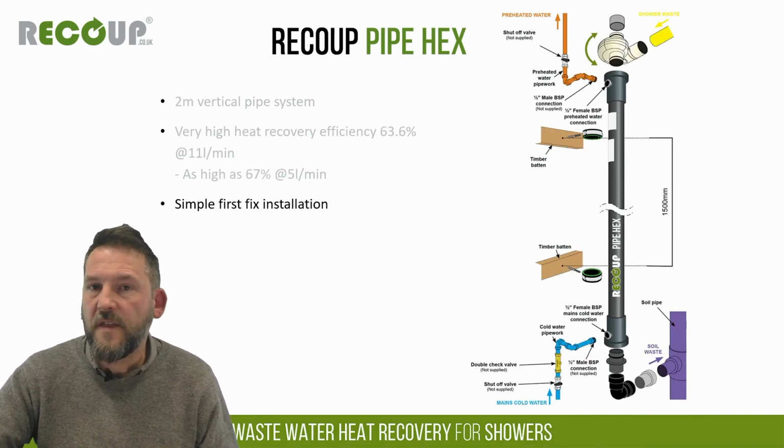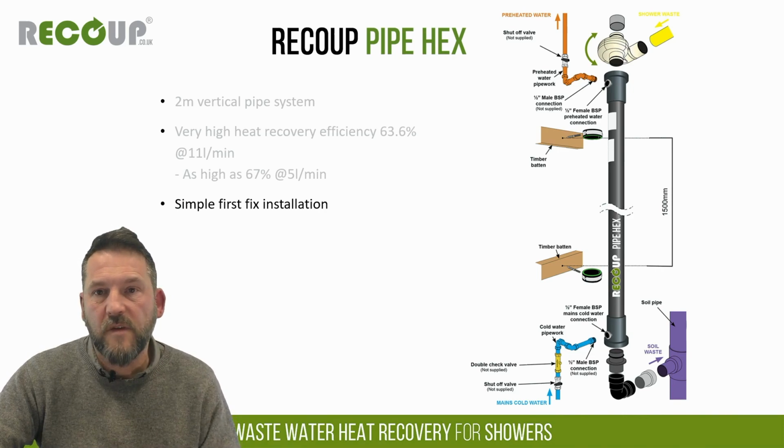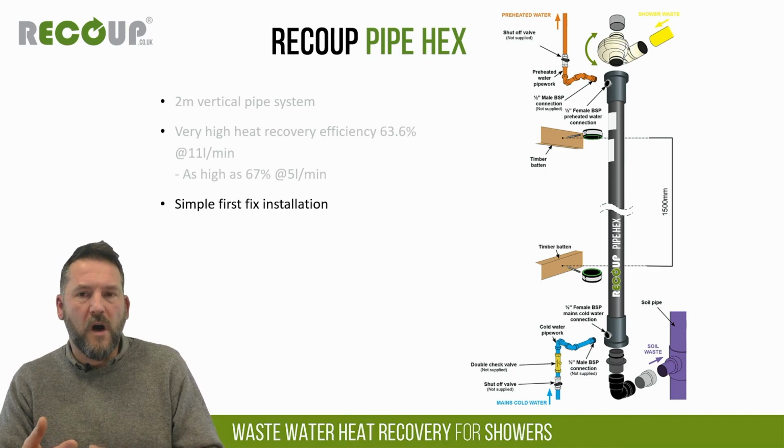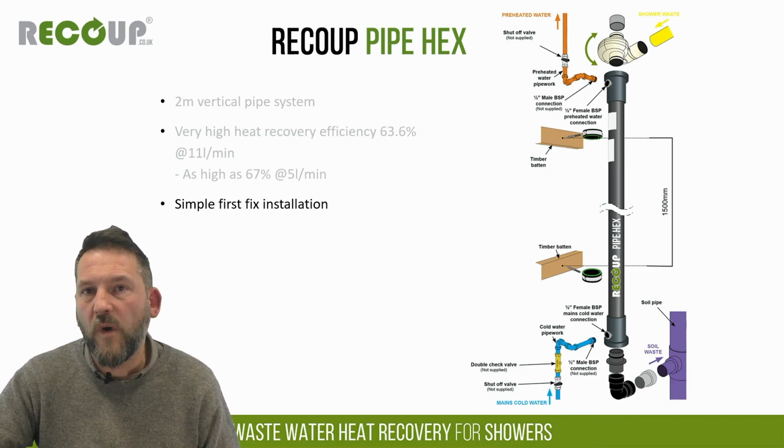So as you can see here, this is a standard setup. So we've got the waste coming into the turbo rotator, drops down through the wastewater heat recovery unit, and then just vents off to the SVP as normal. So we're not collecting the grey water, we're not storing or harvesting any energy. It's pure heat transfer. And as that warm waste comes down, cold water main comes in, goes around the outside of the unit and comes out preheated.